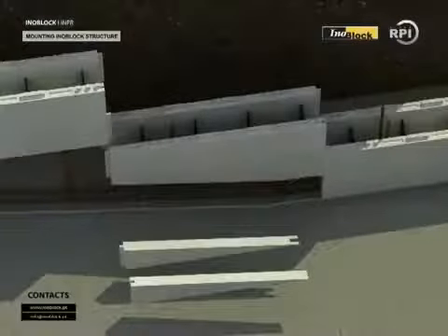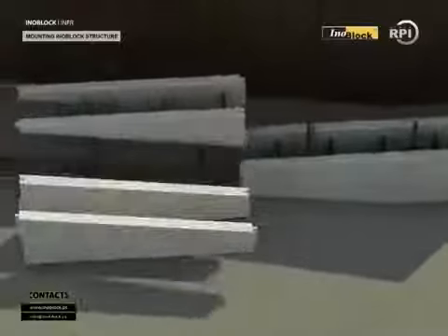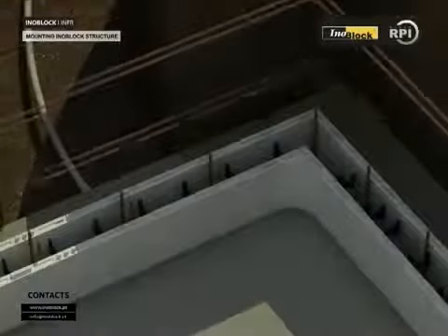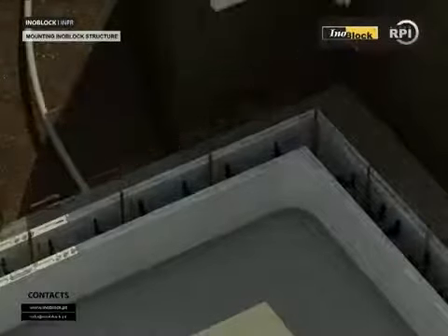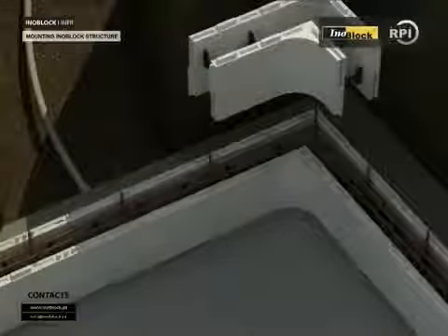Continue to align the blocks around the perimeter of the pool. In a pool of unequal depth, cut the blocks at an angle where the slope starts. After the first row of blocks is completed, place 2 or 4 rings of 8 mm steel reinforcing bars. Continue with the second row, taking care to overlap the blocks. Apply the spray glue in oblique product to join the blocks.